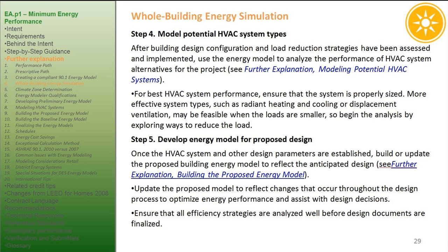For best HVAC system performance, ensure that the system is properly sized. More effective system types, such as radiant heating and cooling or displacement ventilation, may be feasible when the loads are smaller, so begin the analysis by exploring ways to reduce the load.